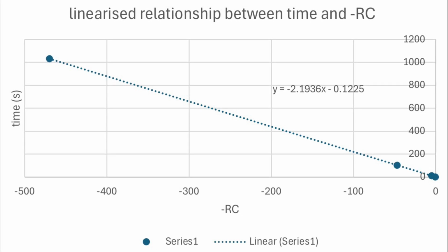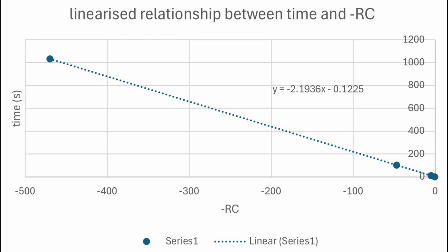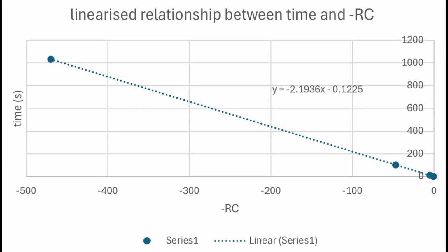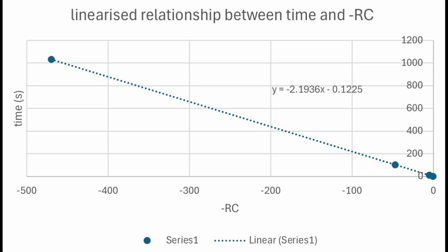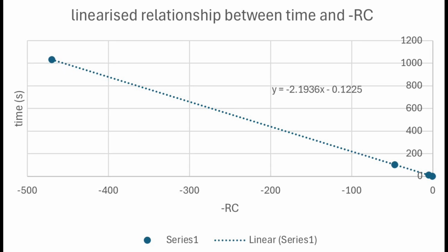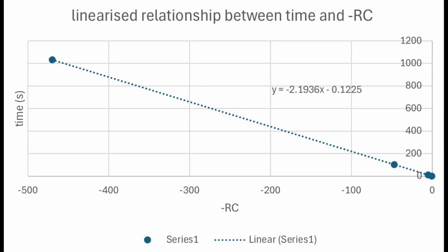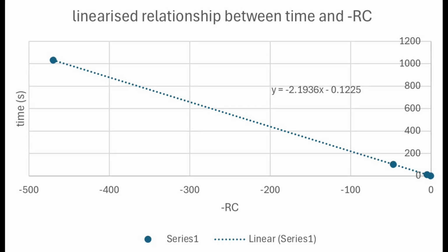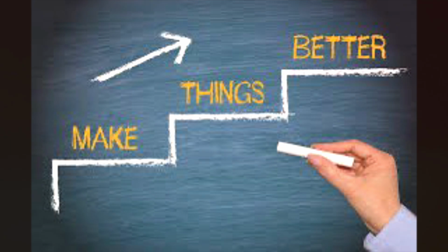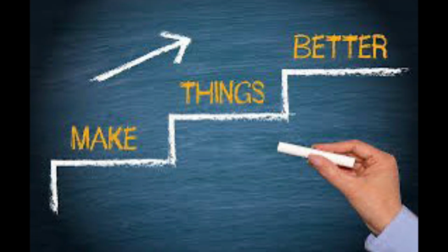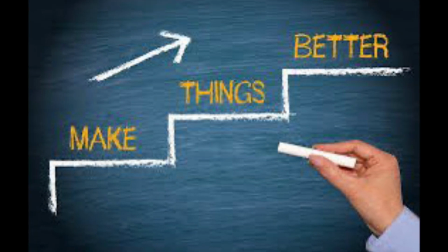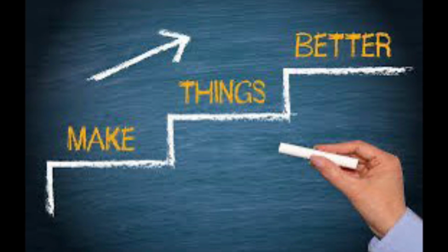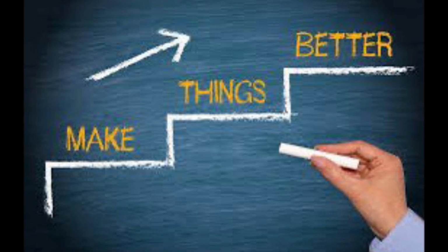The small error was likely caused by uncertainty introduced from the devices used to record the data, such as the oscilloscope that has an uncertainty of plus minus 0.005. The linearized graph demonstrates the theoretical gradient of ln 1 over 9 is represented in the experimental data with an error of only 0.1649. To improve the experiment, it is recommended that higher precision measurements are taken of both the time and the resistance, as without verification it can prevent the data from reflecting the theoretical relationship.